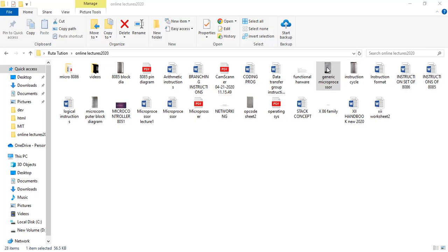Then they have shown the clock block, which gives the clock crystal chip inputs, and the clock signal is going out and it is given to the timing and control. Then plus 5 volt and ground are the supply voltages. Then data bus D0 to D7, address bus A0 to A15, 16 bit. And then this is your ALU section, accumulator and temporary register. And the flag register is now inside the ALU, they have shown. Complementer and shifter are used for addition and subtraction. Two's complement method you do the subtraction.